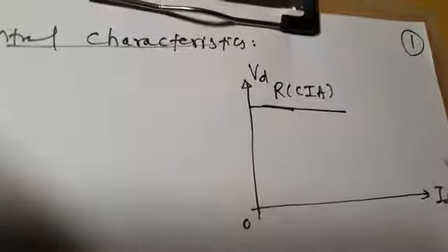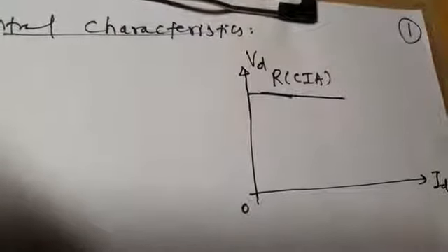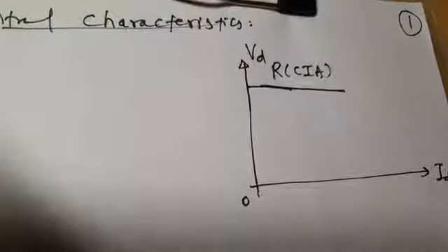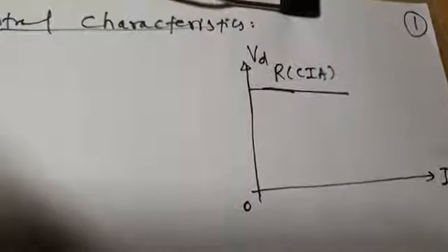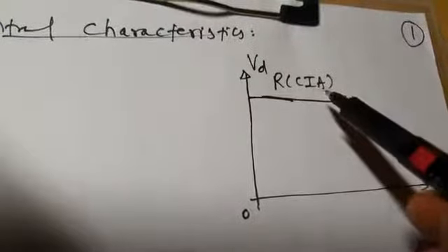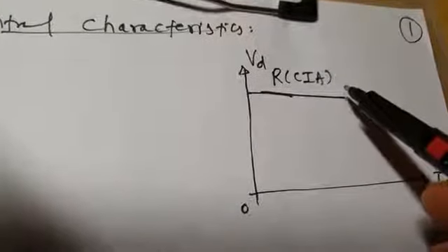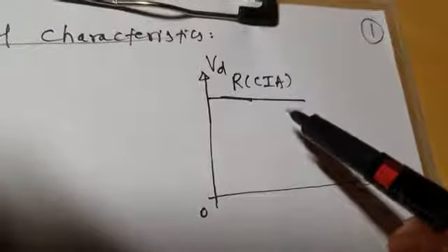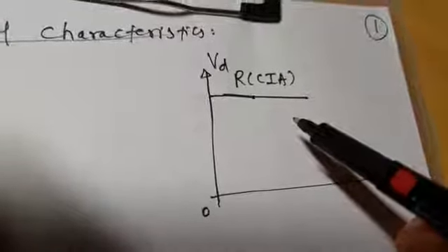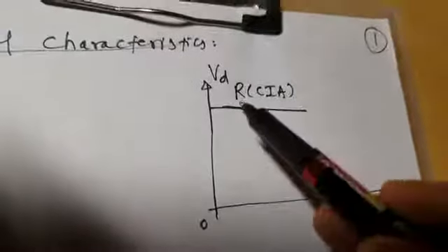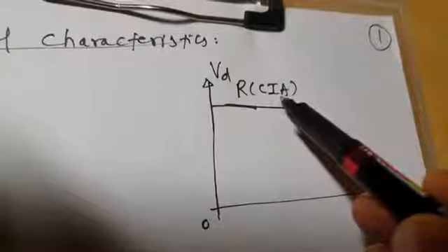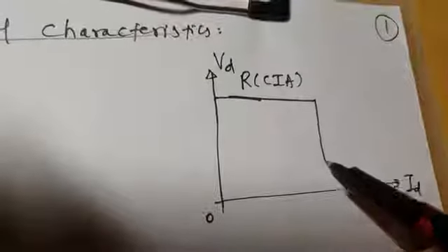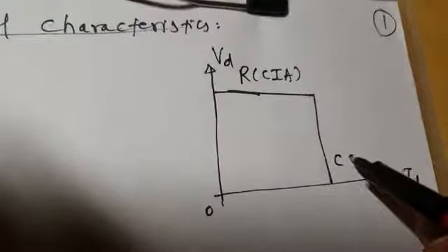Alpha is not allowed to go beyond alpha max, and alpha max, for avoiding large reactive power, the maximum delay angle is 20 to 25 degrees. So alpha greater than alpha max is not possible in this case. And alpha less than alpha min, which is around 5 degrees, is also not allowed by the controller. Now this is the rectifier characteristic, the constant ignition angle control characteristic, followed by the constant current characteristic, CC.